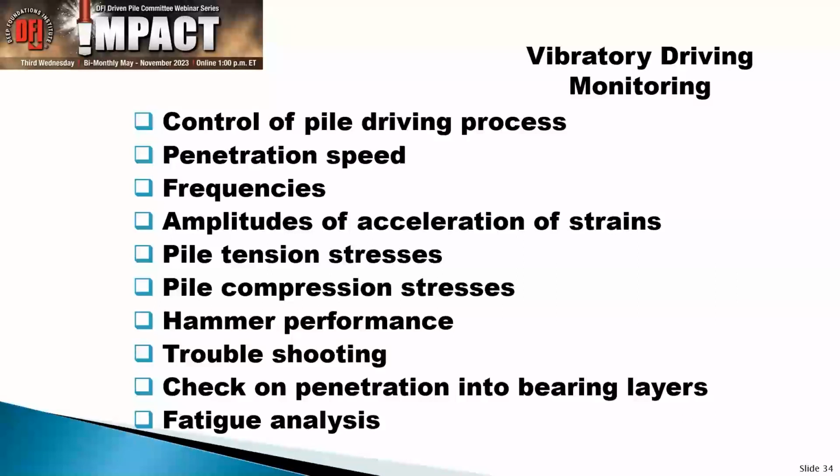And then we start doing monitoring. And with the monitoring, we do exactly the same thing that you do with your pile driving with an impact hammer, but there are a couple things that are different in there. You see that we are monitoring the frequencies as well. You need to figure out what the frequency is of the vibratory hammer, because if that changes, as we're going to see in a little bit, that may have an impact on how you drive your pile into the ground. If we look at the stresses, both tension and compression, we'll look at the hammer performance, we'll look at the troubleshooting, and then you also see that we have a fatigue analysis.